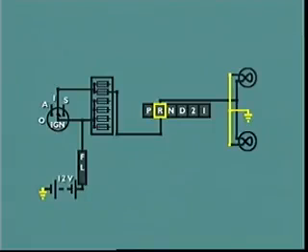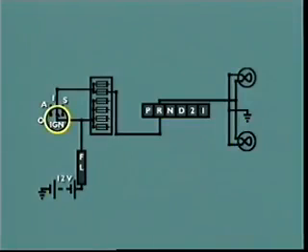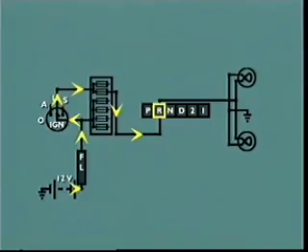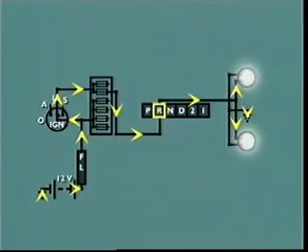When the ignition switch is on and the vehicle is placed in reverse gear, current flows from the battery through the ignition switch to the closed reversing light switch on the transmission. Electrical current flows across the closed switch to the reversing lights and then returns to the battery by the earth return system.